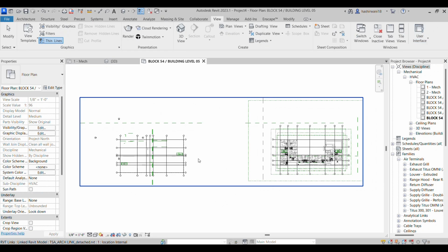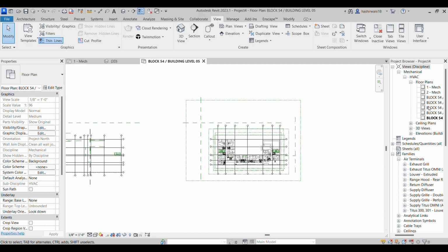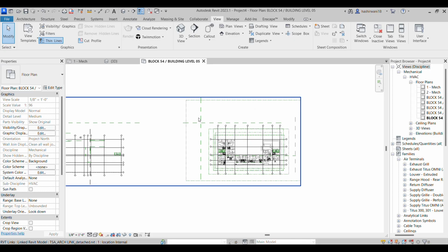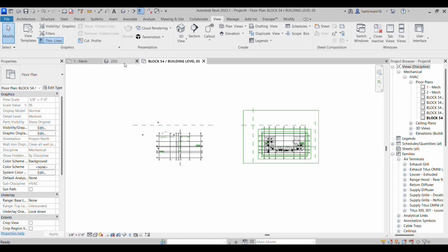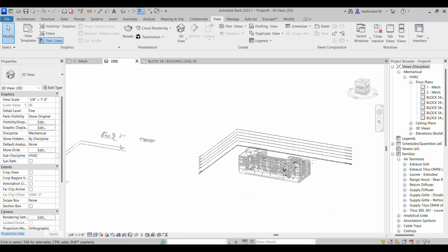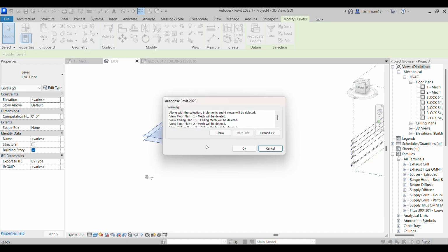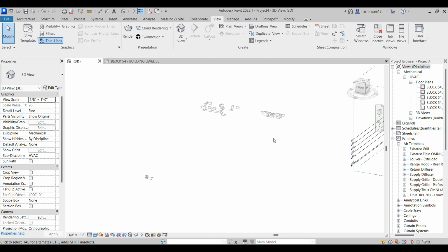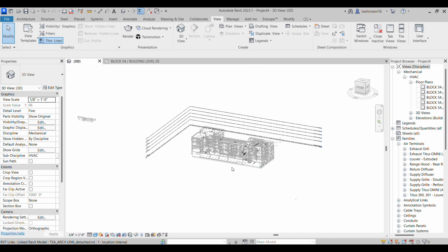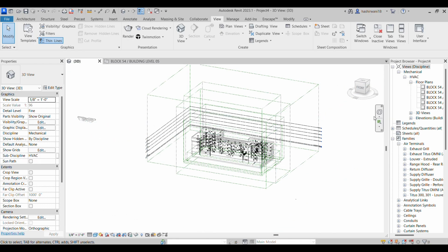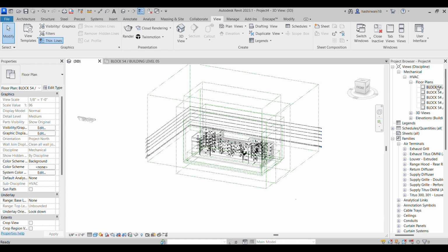We'll make it full screen now. Can you see, guys, my floor plans have been created, but we still have these particular mechanical 1, mechanical 2 from our mechanical template. So we don't want these because these are of no use. You can simply select them here and delete them, and now they have been deleted. Now the next thing, I'll go to the first floor level, this one.